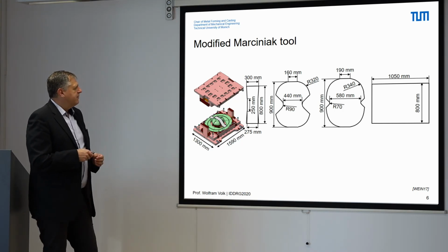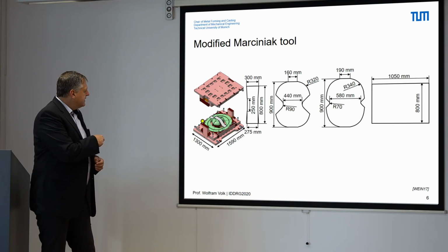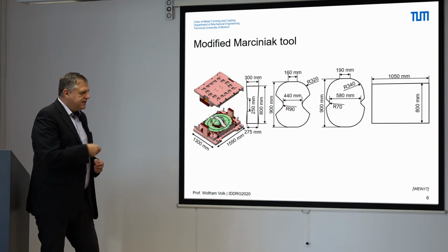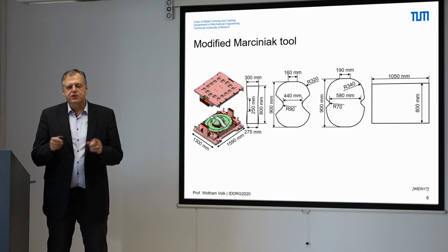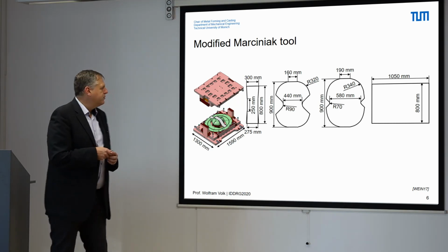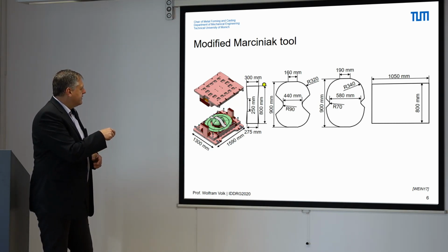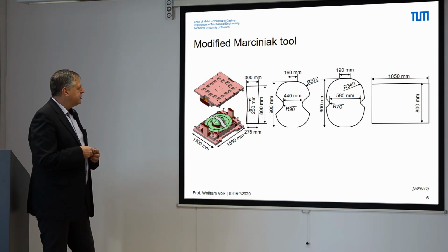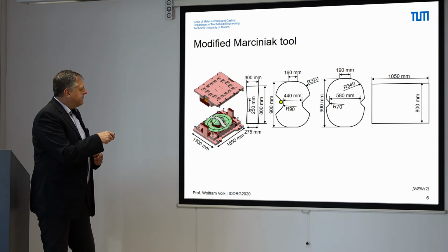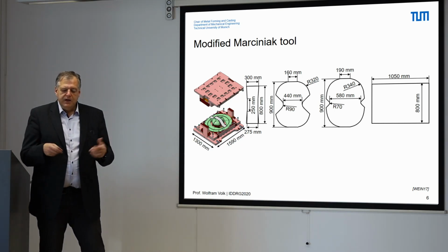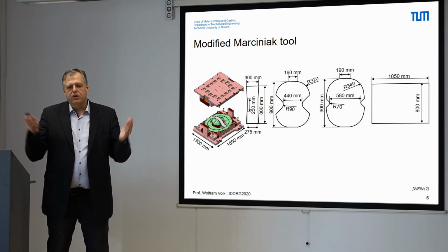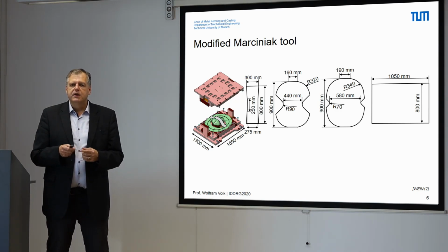And what's the big benefit of such a tool? You can realize any desired preforming step just by changing the blank within the same tool. Here we have the small sized one for the uniaxial tension, then these butterfly shaped specimens for plane strain and multi-axial strain, and the big one for biaxial strains. With this tool, we proposed our non-proportional load paths so far.